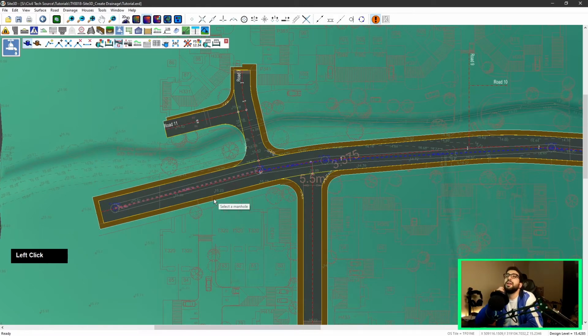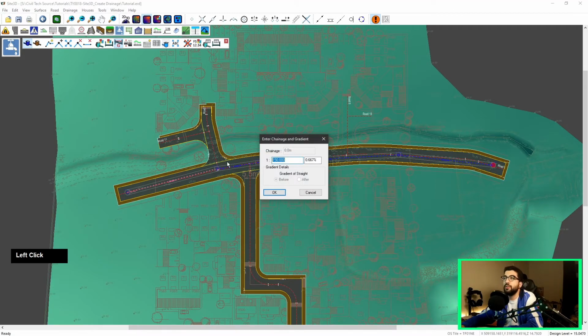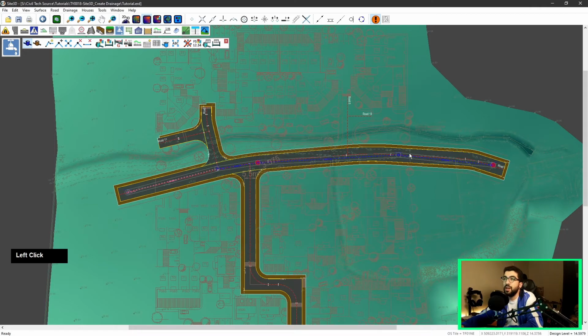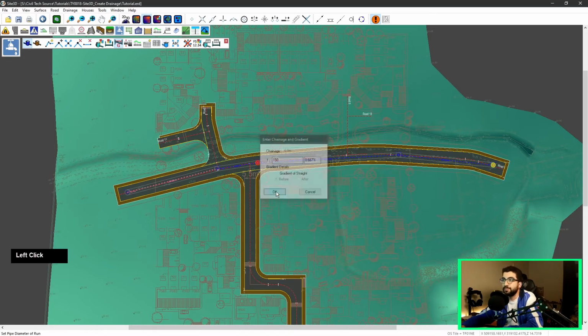Now, the next command is the set gradient run. Now, this command I had not a hard time, but kind of like a few minutes to understand why it works that way. So basically, we can set the gradient from there to there. These pipes are in a standard gradient. So let's say if I want to do from here all the way to here, we want the gradient 100 because the pipe is like 150. So we hit OK. And then if we do the gradient again from here, let's say to here to 150.